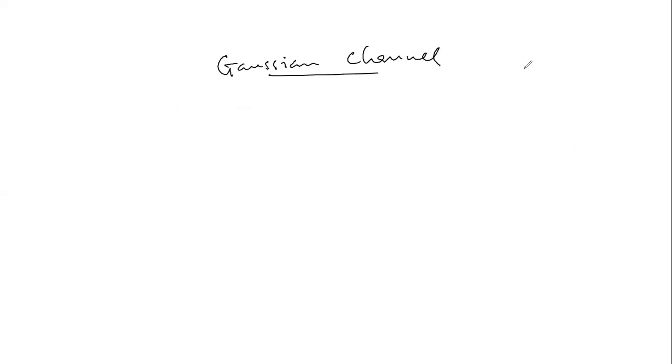Okay, so in your communication system, you must have heard of a Gaussian channel, a Rayleigh channel, a Rician channel, and all of that. In the practical sense, when we have a direct line of sight between your transceivers, then we actually deal with a Gaussian channel. Most of the time, this is what we have in cable when we use cable as the medium of communication for your wired communication, even your direct microwave link point to point. So we deal with Gaussian.